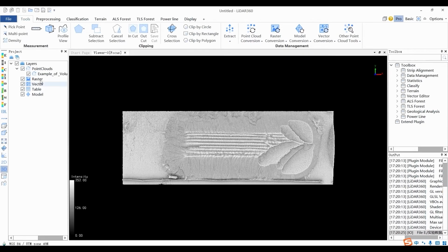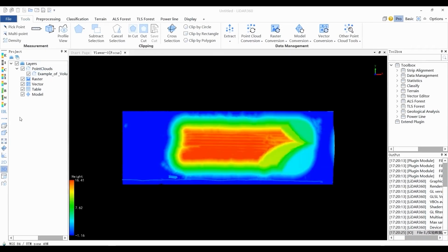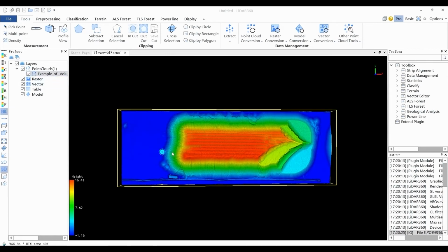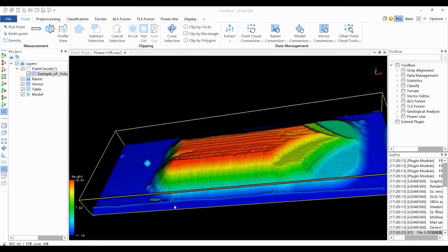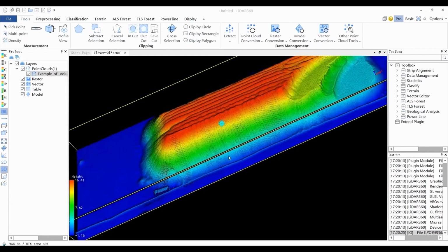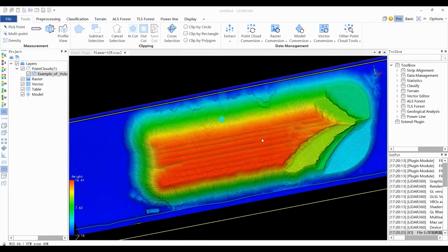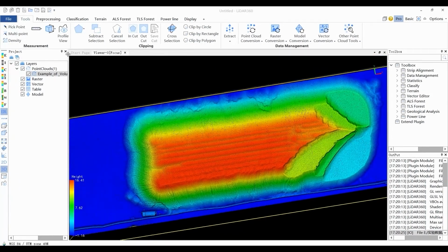Cell size defines the smallest unit size for calculation. The smaller the value, the more accurate the calculation is. Basic height defines the reference plane to calculate the filling and cutting data source. Specify the points used to calculate the volume. This tool only works with point cloud data and model data in 3D view.